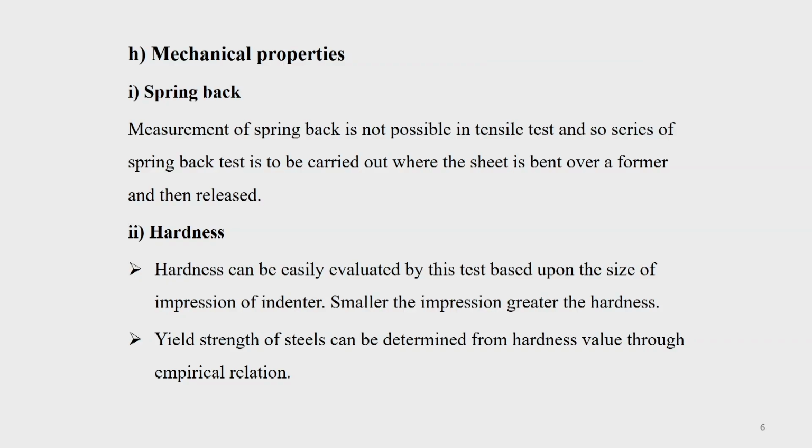In most steels, the yield strength can be correlated to the hardness, but this is generally not practiced in non-ferrous materials. These correlations are basically indicated in steels. People have carried out extensive work trying to correlate between the strength and the hardness of steel. When you do different heat treatments and get different hardness, your strength also changes. So that information is already available.